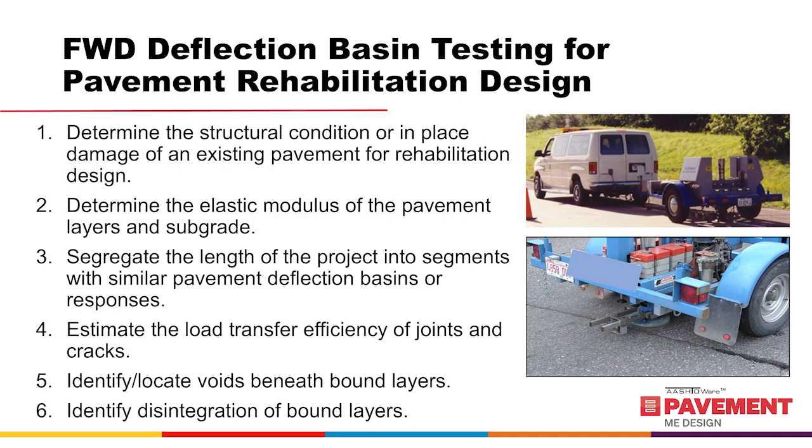The second area is to use deflection basins or structural responses of the existing pavement structure to back-calculate the elastic layer moduli for structural layers and subgrade for asphalt or flexible and rigid pavements. The in-place elastic moduli are used to determine the conditions of the structural layers. The third area is to segregate the project into areas with similar pavement responses or deflections. This area is used to strategically locate borings and cores to confirm the layers, condition of the layers, and subsurface